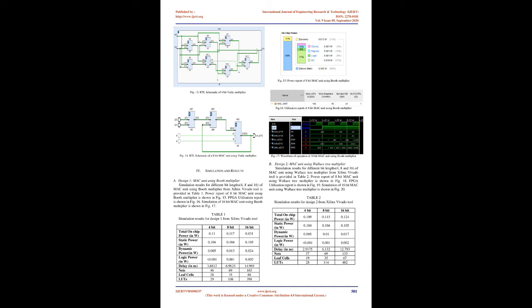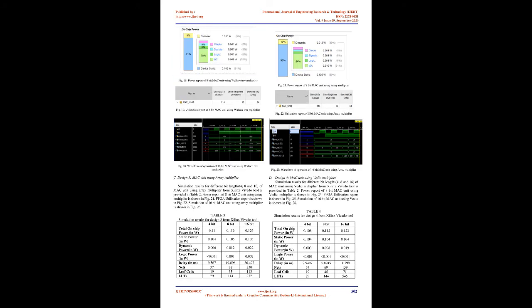1. Booth multiplier. The Booth multiplier follows Booth's multiplication algorithm, invented by Andrew Donald Booth in 1950. It multiplies two signed binary numbers in 2's complement notation while preserving the sign of the result. It outperforms earlier methods of multiplication by reducing the number of iteration steps. It scans the multiplier operand and skips chains of the algorithm, thus reducing the number of additions required to produce the result.